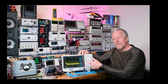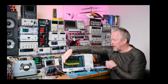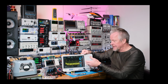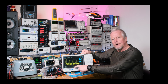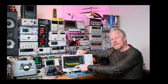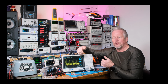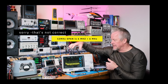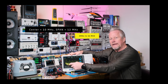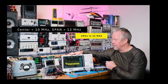Like on this thing, when you set up the frequencies you want to look at, there are two different ways. You can say, I want to start here and end here, start and stop. Or, which a lot of people use, you say my center frequency is going to be here, and my span is going to be this. So my center frequency could be the 10 megahertz clock, like I have coming in here, and my span is going to be 2 megahertz. So it'll be 1 megahertz on this side of it and 1 megahertz on this side. I could just say it's going to start at 9 and end at 11. So it's just two different ways to do it, right?